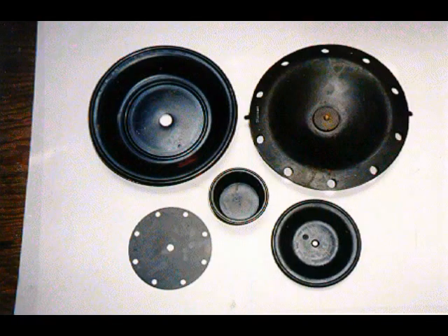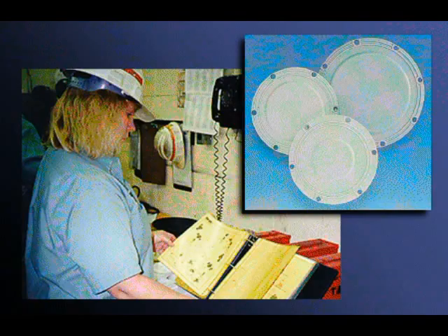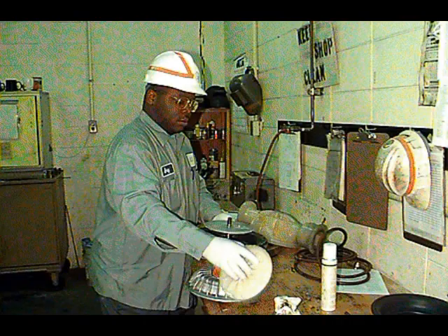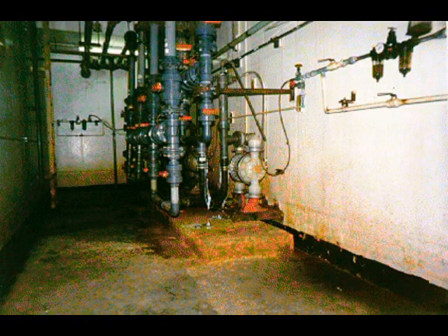Operators may also need to replace the diaphragms from time to time. Replacing the diaphragm is not difficult, but an equipment manual will be helpful. To install a diaphragm, first remove the pump head. Run the pump at its slowest speed, and turn it off when the diaphragm is farthest out from the pump housing. Follow the standard lockout-tagout procedure, and be sure to lock out the air supply to the pump. Make sure to replace the pump head with the discharge valve on top, and the head in the vertical position. Also be sure to tighten the pump head screws evenly.